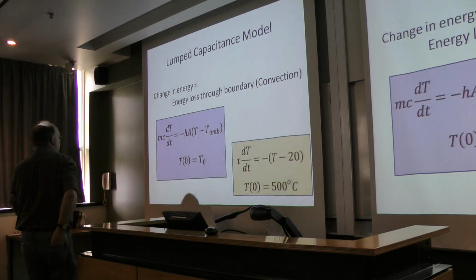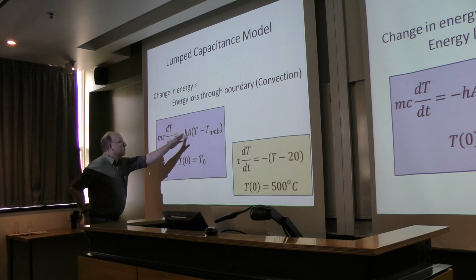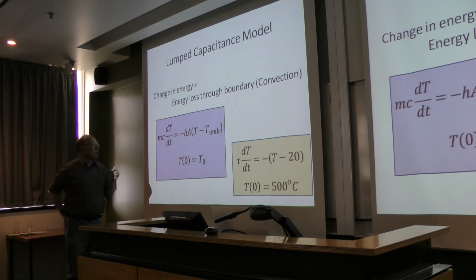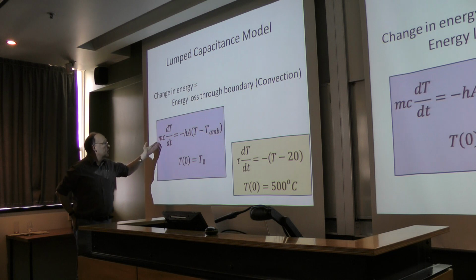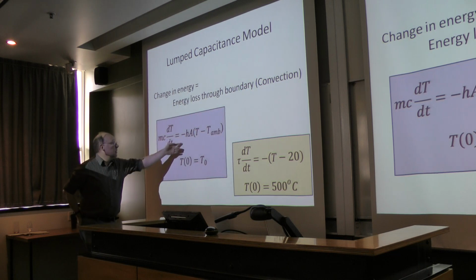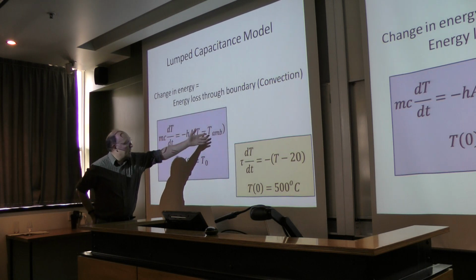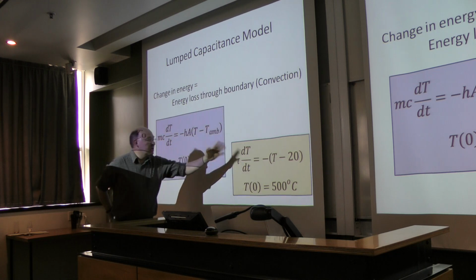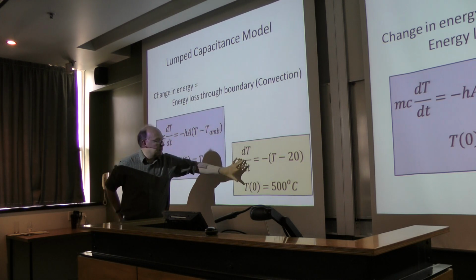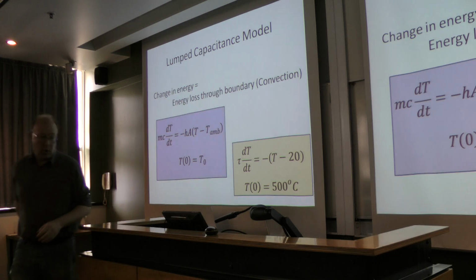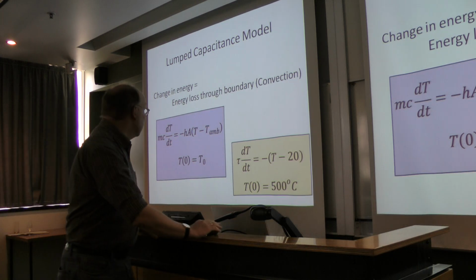They're confused by it by and large because of all the different parameters in there, but most of them are constants. You've got the mass, you've got the specific heat capacity, heat transfer coefficient, area, ambient temperature. If you put in most of the values that you know in that, then you end up with something that's far more simple, which they're not afraid of, whereas the other one they probably are.